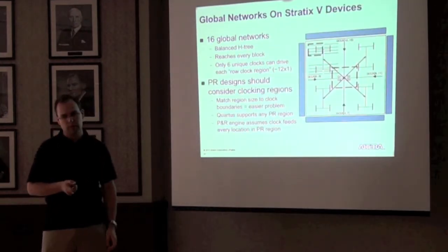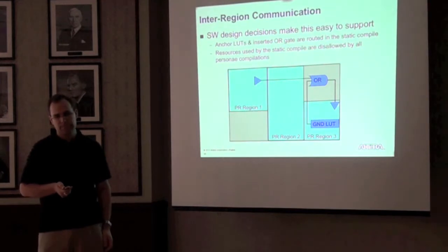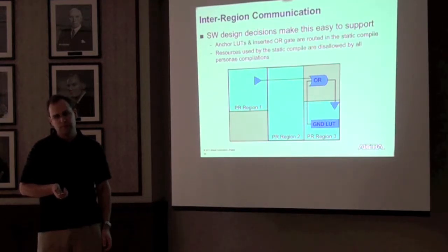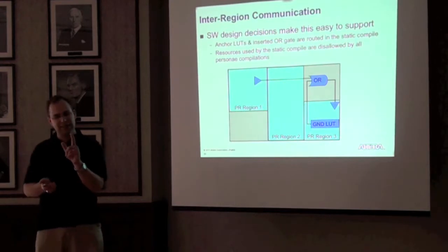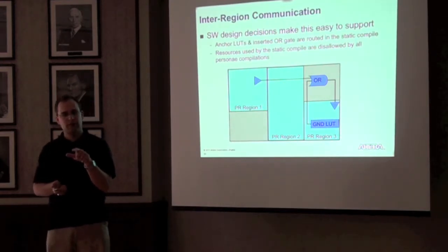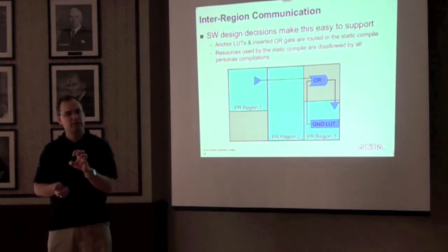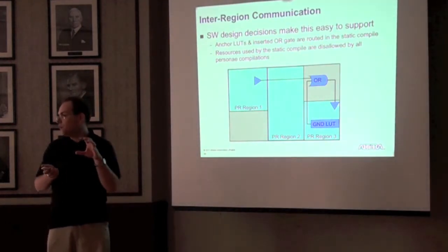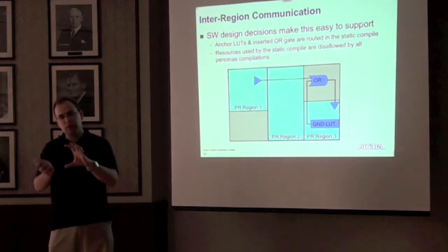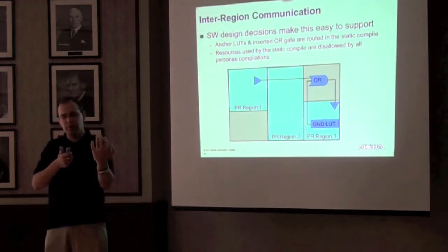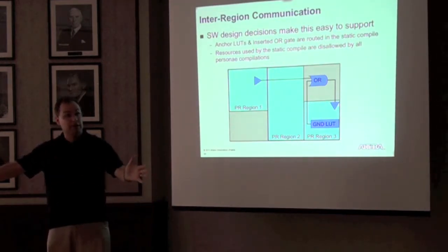Isn't there an order of compilation issue that shows up then? Because when you do PR2, you have to kind of know the PR1 and PR3 want to talk. No, because all the blue logic here is compiled before any personas are even being done, using incremental compile. This is part of the base revision. We import that placement and routing. And so whether you do PR1, PR2, PR3, in fact, all in parallel,